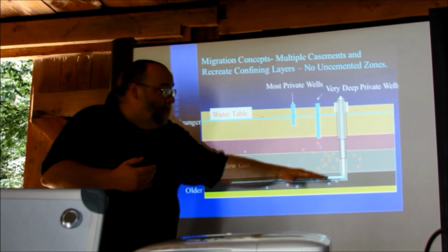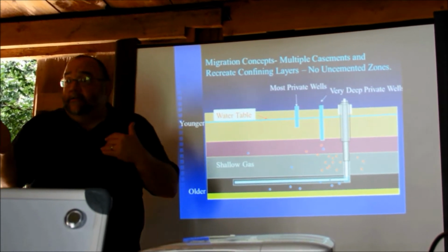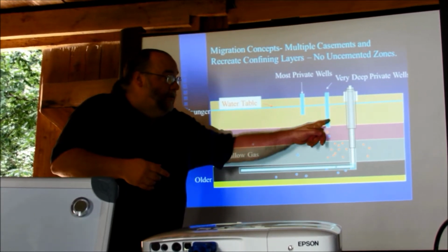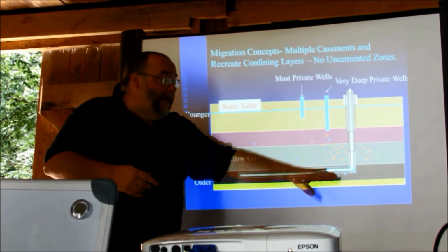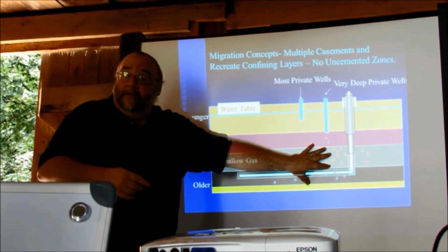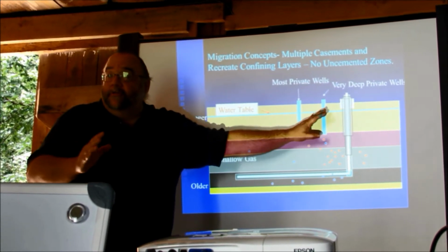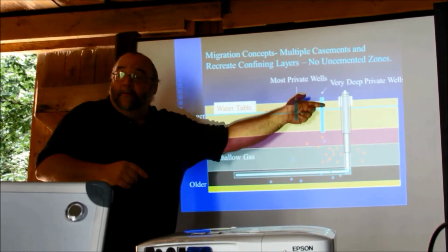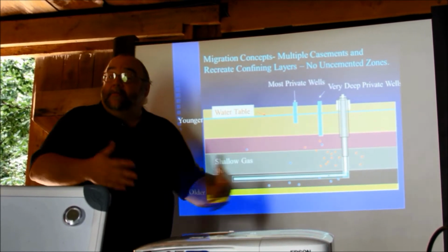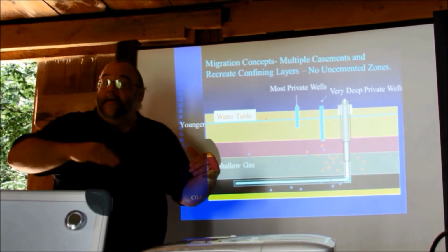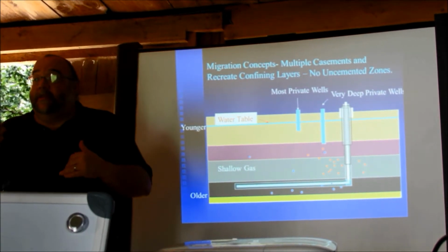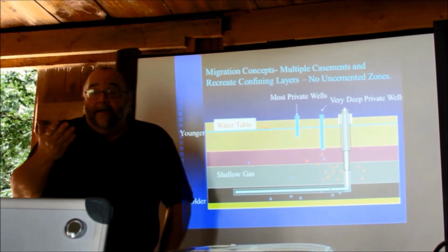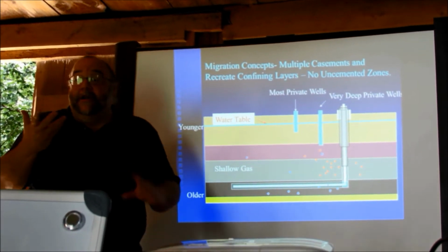If a pressure migration occurs, pressure moves instantaneously. So if you have a pressure wave migrating that causes a water level change here, you haven't had any movement of fluid from here yet. You just had pressure move. And so if they start hydrofracking, that water level goes up, and they stop and it goes down, that means the pressure moved, and so there's some connectivity, some connection. Did things move from here to here? Maybe not yet, but at least that's the easiest way to check and monitor.